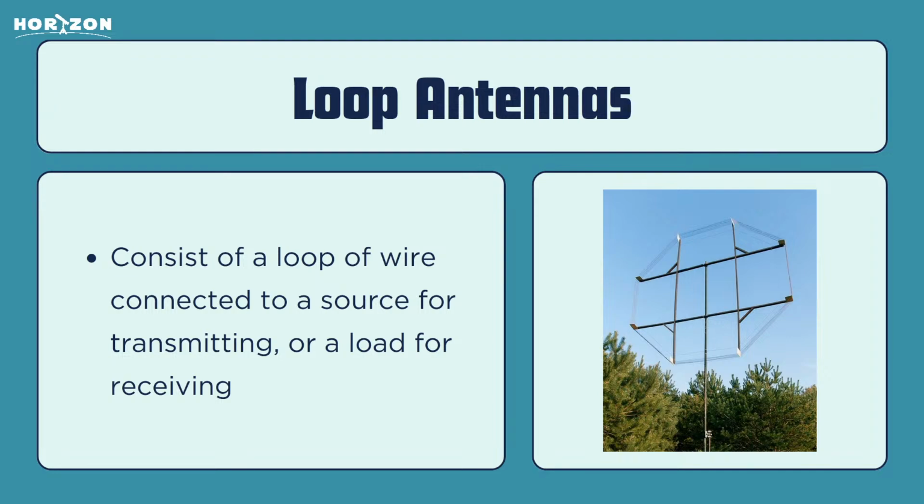You would get standing waves and fixed nodes and antinodes, similar to the dipole case. You'll have a maximum current at the antinodes, and you'll have maximum efficiency when the perimeter is equal to n lambda.